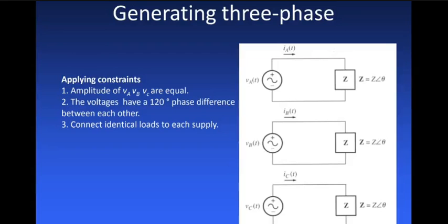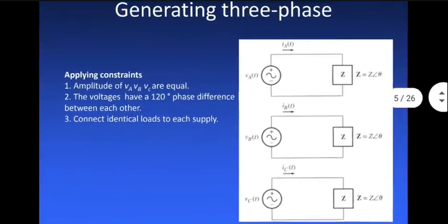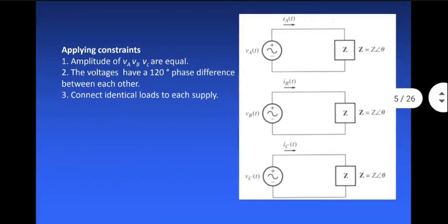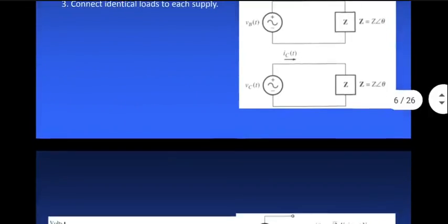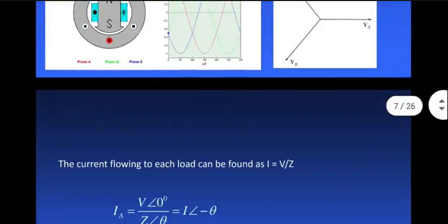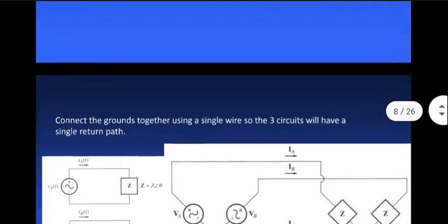Three phase. Here, what he's doing is showing each phase, that means each generator, independently, assuming that the load is balanced. All the arms are equal in impedance. But the voltages have a 120-degree phase shift throughout. The waveforms are going to be shifted by 120 degrees, obviously. Avoid theory right now. We'll do that next time. He's showing you how to do calculations of currents. I'll do it anyway in detail in my own notes.